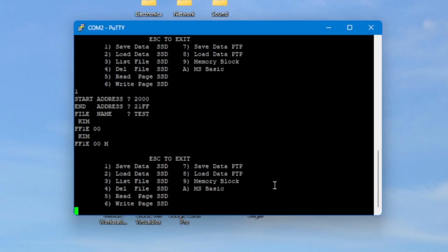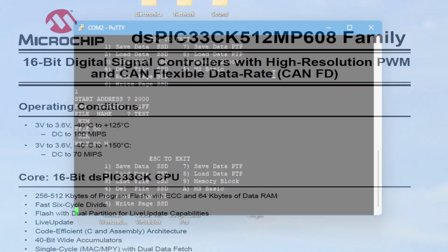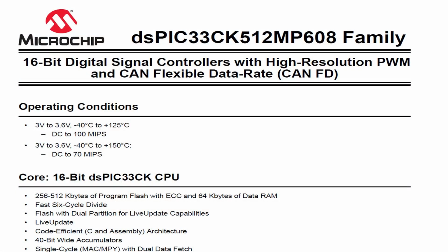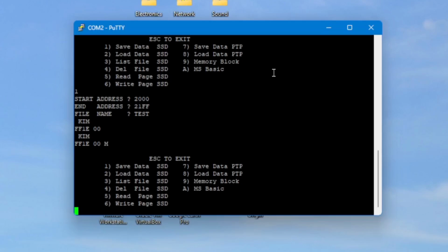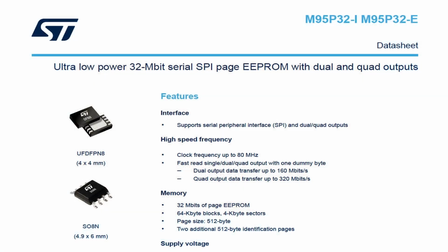Our simplified version of a FAT32, just don't know what to call this one. No, KIM DOS. But we go through that, and then in the video after that, we go into more detail of how the microcontroller actually pushes and shoves things around. We won't actually be going too detailed into the code of the microcontroller. Be more of a sort of a block diagrammy thing, not too much in the code. And it'll show you how to handshake back to the KIM and how you get things synchronized up and how it reads and writes things, and how you talk to the EEPROM.